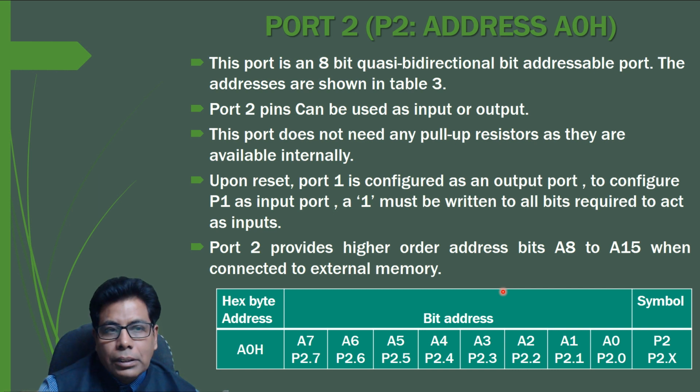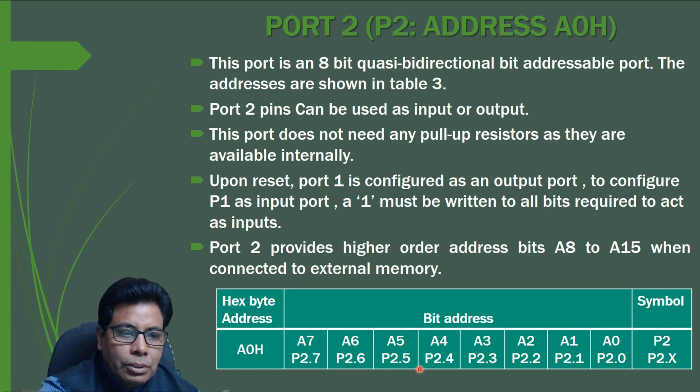Here this port is also an 8-bit bidirectional bit addressable port, similar to port 1. So the addresses are shown here. The byte address is A0 and the bit addresses are given here. So A0 to A7, these are the bit addresses for the respective pins.